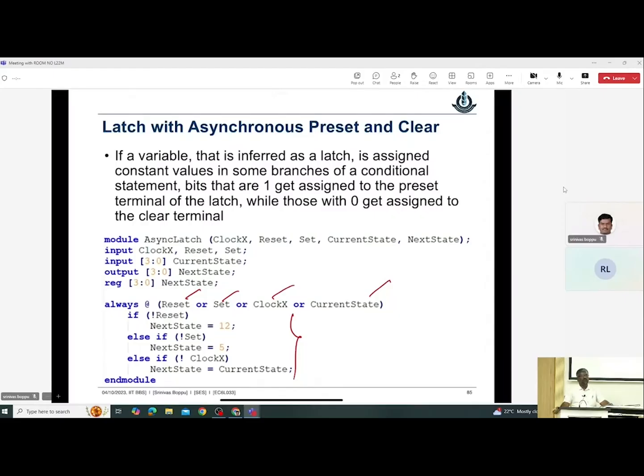Now how do we really get the logic correctly? We were thinking about a D latch. We have a D input, Q, and we have enable, and now we have a preset pin and a reset pin. Again the preset could be active high or active low, and the reset could be active high or active low. Whatever circuit comes out depends upon what kind of cells I have, right. Is that clear so far?